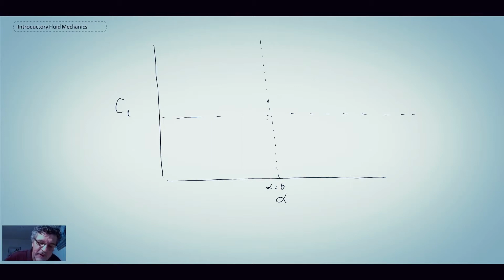What they would do is go in and do this alpha sweep, and using a force balance, measure the lift coefficient as a function of angle. Eventually you get up in here where the lift drops all of a sudden. This is the onset of separated flow, and this is what they refer to as stall.